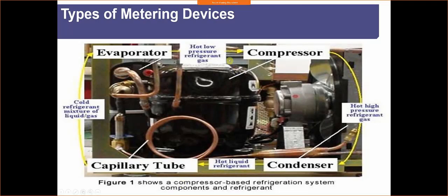So this is just an example of a capillary tube. I've got my compressor right here, and I've got this coil of tubing right here. All right, so my refrigerant flows through this tube, and you can see how much of a difference in size it is in thickness here. Maybe like a 3/8 comes in, and then all of a sudden it drops down into this really tiny fine tube, maybe from 3/8 to 1/8, and that just causes that whole reactionary process to go through.